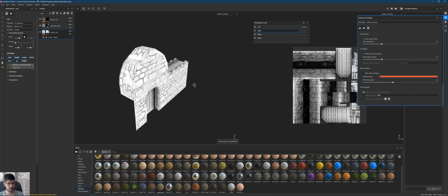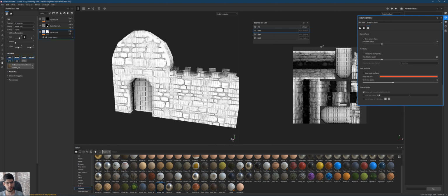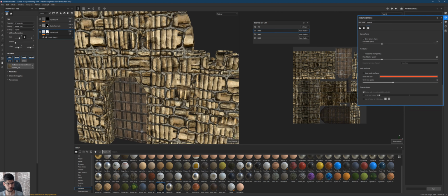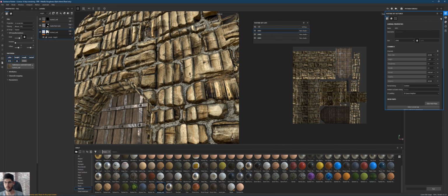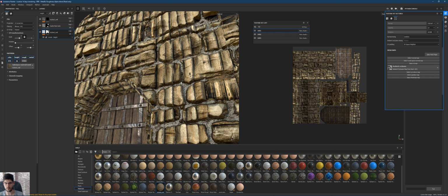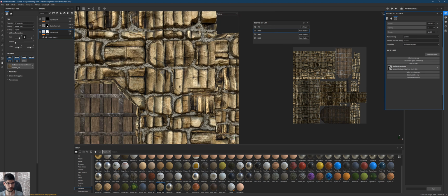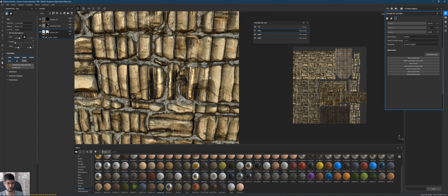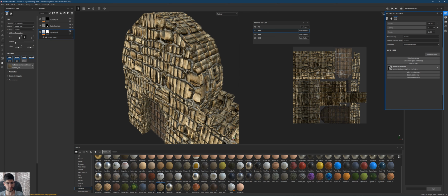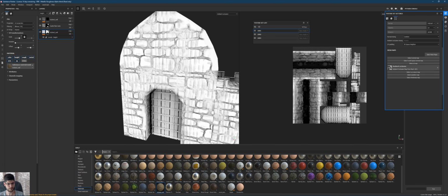So as you can see now, this is done. Basically, we have the ambient occlusion generated. And if we press M on the keyboard to go back, you can sort of see the ambient occlusion over here. If we go into our texture sets and we have a look at the ambient occlusion, if we deactivate it, then you can see a bit of loss of shadow there from the ambient bake. Can't really tell that much over here on this texture. It's all dependent on the textures you're going to use, but you can clearly see it over here, right? This is the ambient occlusion that we've baked.